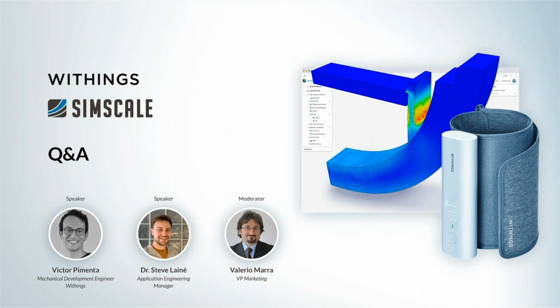So in this case, it's linked to the physical contact. As the PCB is the more rigid part, as it is a stiffer part, we define it as the master surface. So it's a fixed, let's say, entity. In this case, it still can deform, but the plastic casing was the part with more deformation.